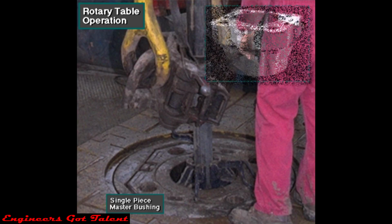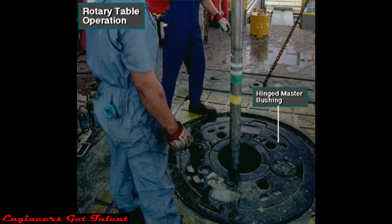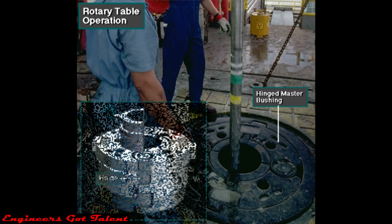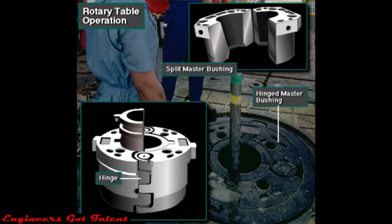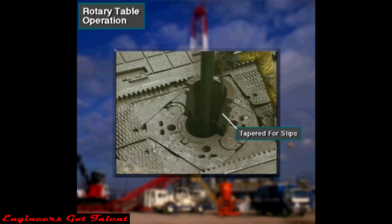Small master bushings are usually a solid single piece, as shown here. Large master bushings are either split or hinged. Crew members install a 2-piece or split insert bowl in a receptacle in the center of the master bushing. The insert bowl is tapered inside and supports the back of the slips.